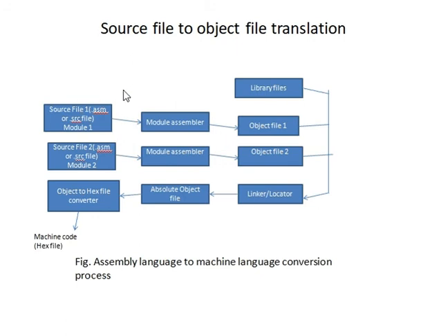So far, if I'm not wrong, two assembly level programs we have executed in part A. One is finding the sum of 10 numbers, and one more is multiplying two 16-bit numbers. So in both programs we had only one file, so you can think of it as your source file. You were not having a second source file. So module assembler would give you its equivalent object file for a particular module, and we require this library now because there are some symbols which are not resolved.